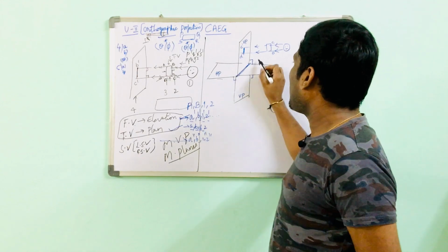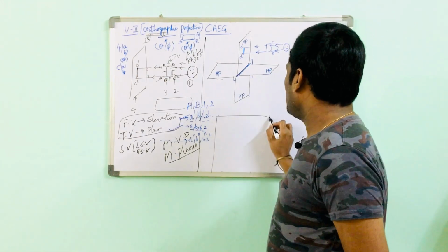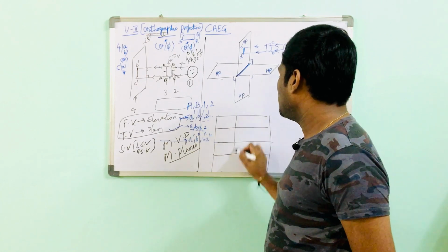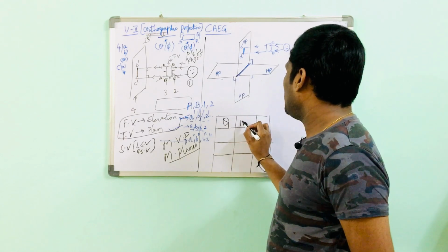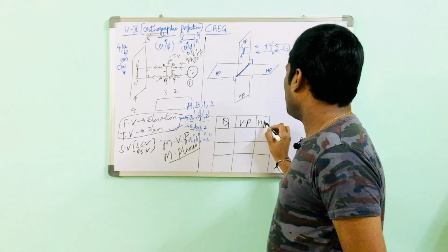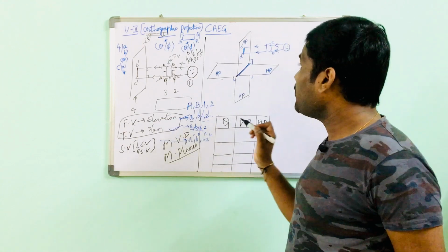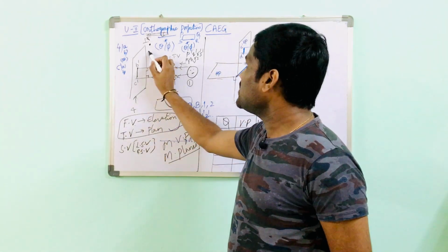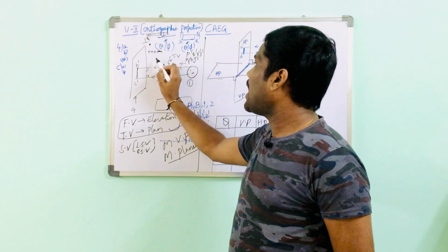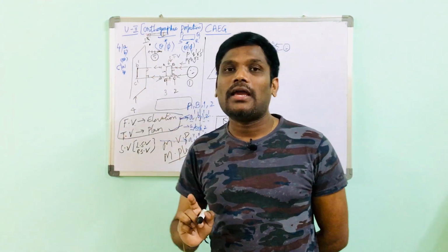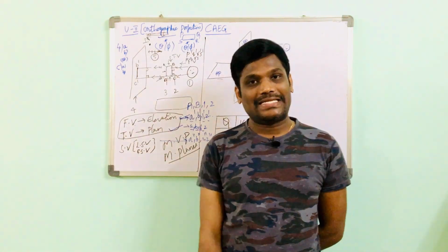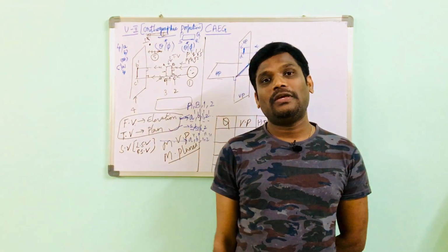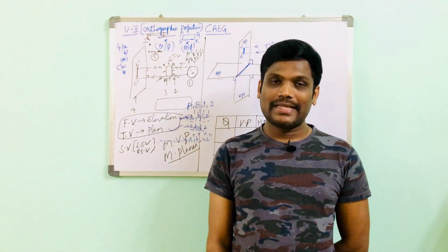Later, if you look at this, we have the box, I mean the views for all the quadrants. We are going to work out the four quadrants here, along with the vertical plane and the horizontal plane. This may also be asked if a problem on orthographic projection of points, placed on a single reference line, is asked. They may ask the question for 5 marks, or sometimes a 1 mark question is also asked. For example, a point A is 20 above HP and 40 in front of VP. Draw the projections of point A. That is a 1 mark question.